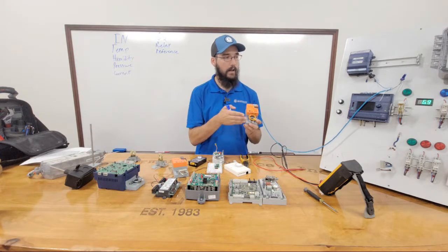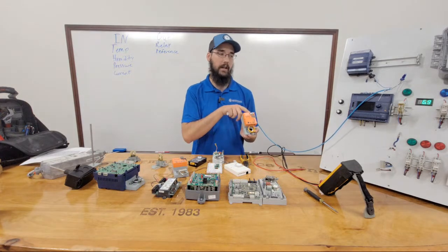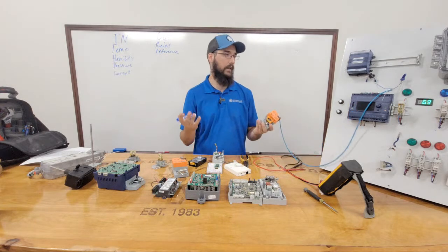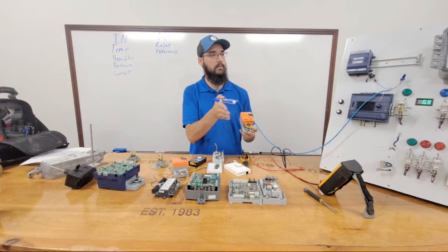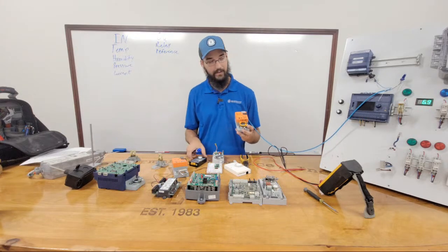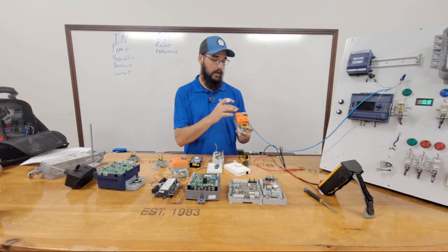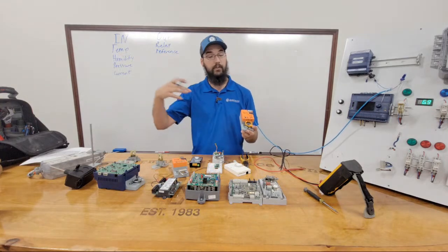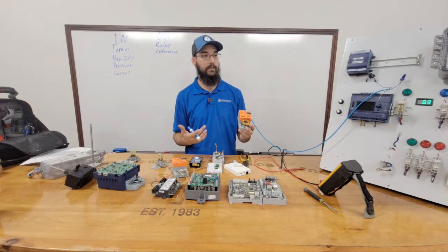So right now, it's in a 0 position because I'm not inputting anything into it. After I give it, say, 10 volts DC, it's going to move into a 100% position. So that is the reference feeding into this actuator, just like we would feed into a VFD.